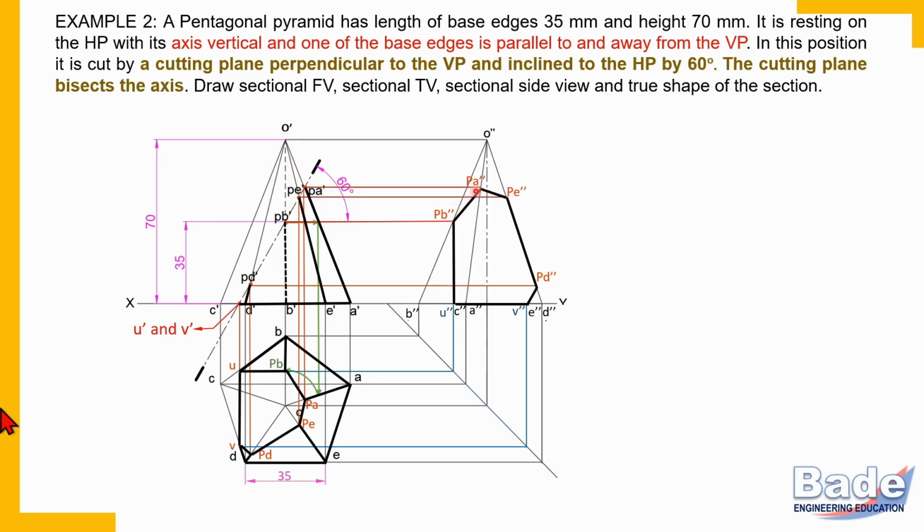So check the boundary of the section here, the upper boundary of the section; above that the portion is removed, and below it the portion is retained. So make the retained portion dark in the side view. So the sectional front view, sectional top view, and sectional side view are complete. The only thing is now we'll have to hatch it.